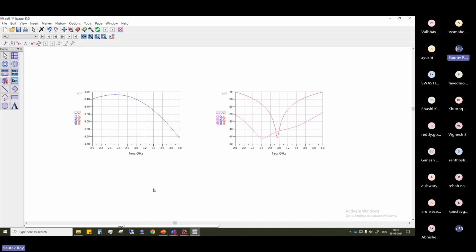No, for those you might be using a waveguide power divider, generally. Those will have better power because they do not have a substrate like this. They are based on very good metals, so they might have very close to 3 dB. But when you do a substrate based design, this might be the problem because of loss and all. FR4 is a lossy substrate, as you know. If you go for RT/duroid or something, it might improve, it might be better.